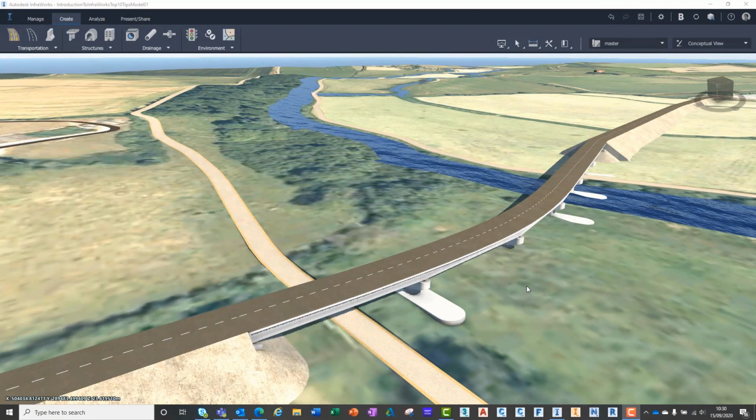Planning roads, however, can instantly change their appearance, whether they're a motorway or a track, with out-of-the-box styles included with InfraWorks. Planning roads are very limited in what you can do with them once created. If required, they can be converted to a component road if the user wishes to further develop them for design purposes or perform any traffic analysis simulations.